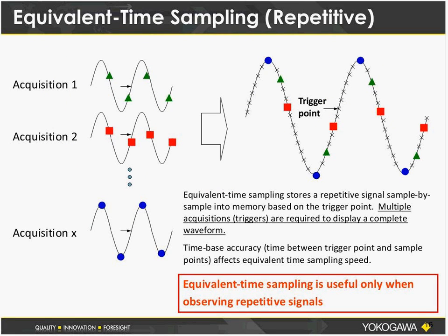A related point in terms of sampling, there is something called equivalent time sampling or repetitive sampling in oscilloscopes. This is a method you can use if you have a repetitive signal to effectively get a much higher sampling rate. Over multiple acquisitions, it shifts the sample clock very slightly, and it builds over time a more detailed picture of the waveform with effectively much higher sample rate.